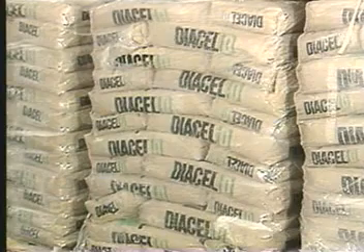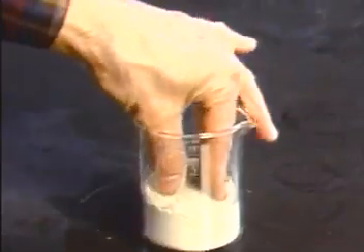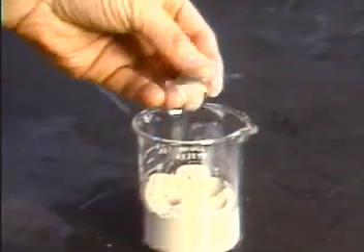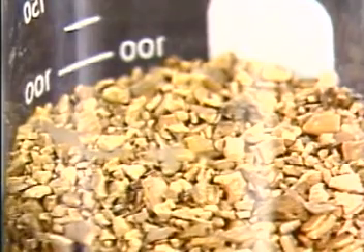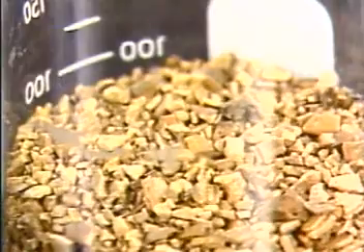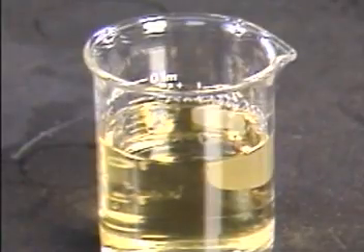Other additives to cement include those also used for drilling fluids and are added for the same reasons. Bentonite for density reduction to avoid formation breakdown. Hematite or barite for density increase to offset high formation pressures. Lost circulation materials to prevent loss of cement into voids, and friction reducers.